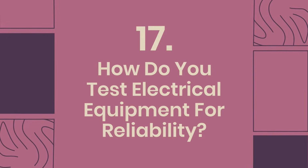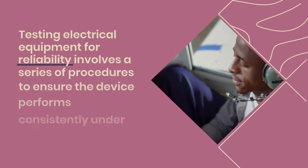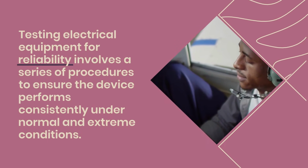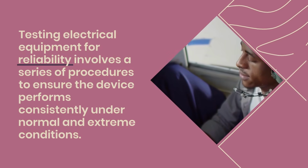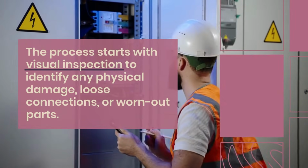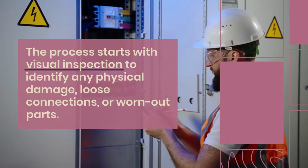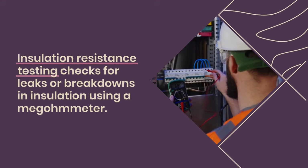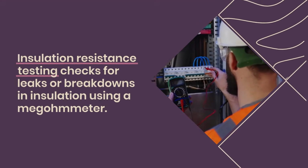17. How do you test electrical equipment for reliability? Testing electrical equipment for reliability involves a series of procedures to ensure the device performs consistently under normal and extreme conditions. The process starts with visual inspection to identify any physical damage, loose connections, or worn-out parts. Insulation resistance testing checks for leaks or breakdowns in insulation using a megohmmeter.